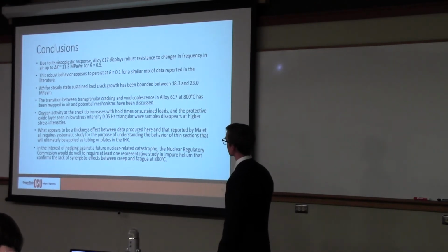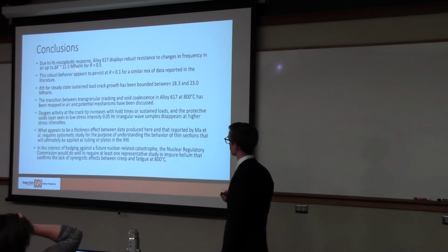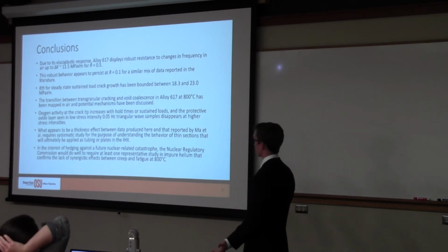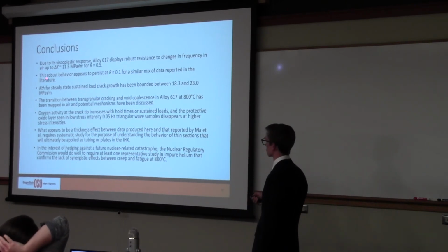That due to its viscoplastic response, alloy 617 displays robust resistance to changes in frequency in air up to delta K equals 11.5 for load ratio of 0.5. This robust behavior appears to persist at R equals 0.1 for a similar mix of data reported in the literature.